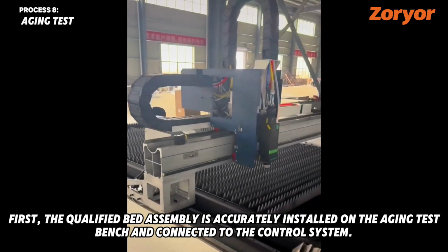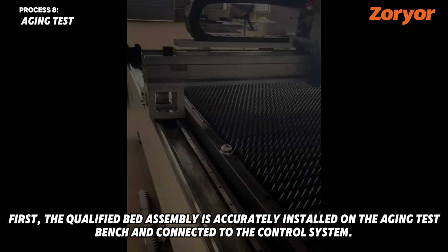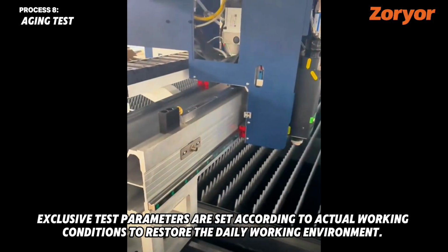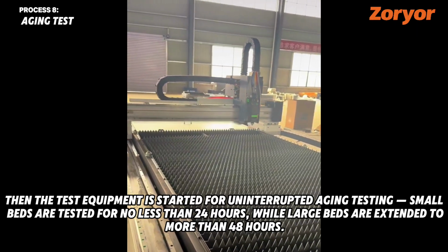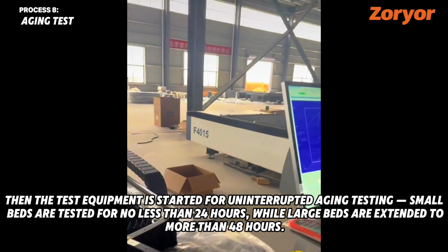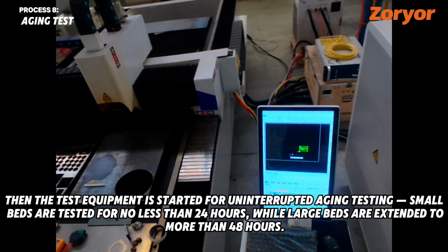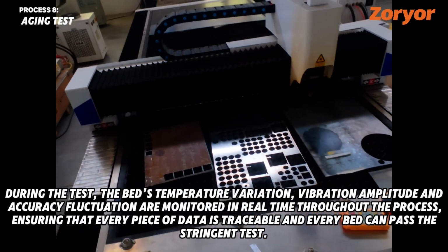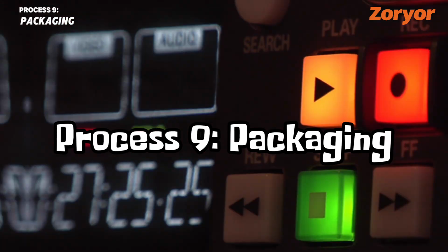First, the qualified bed assembly is accurately installed on the aging test bench and connected to the control system. Exclusive test parameters are set according to actual working conditions to restore the daily working environment. Then the test equipment is started for uninterrupted aging testing. Small beds are tested for no less than 24 hours, while large beds are extended to more than 48 hours. During the test, the bed's temperature variation, vibration amplitude, and accuracy fluctuation are monitored in real time throughout the process, ensuring that every piece of data is traceable and every bed can pass the stringent test.